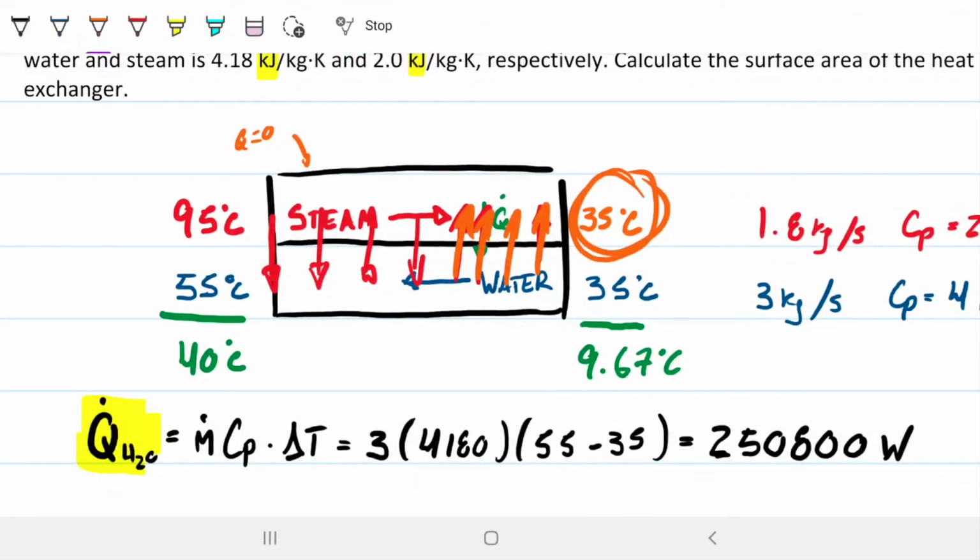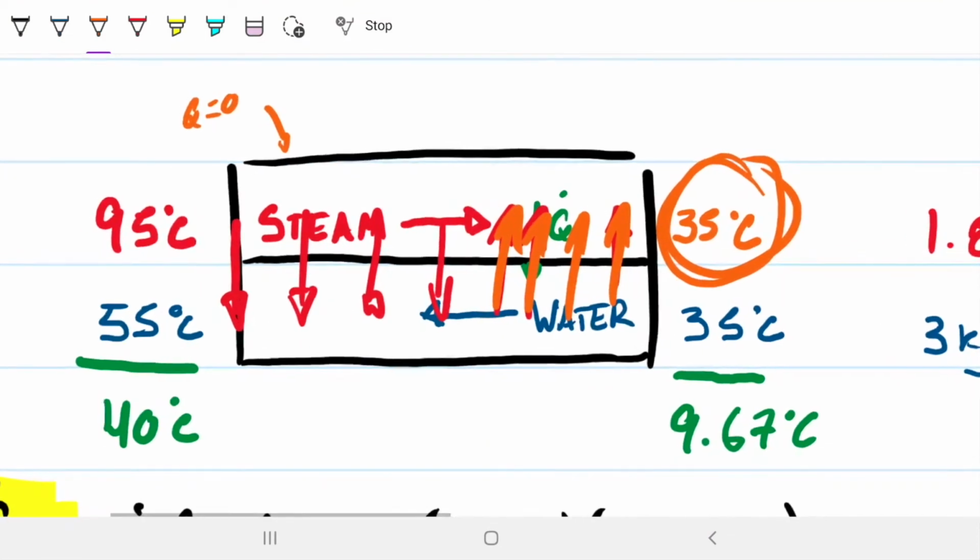So if this were the case, what would be our actual heat exchanger? Let me continue with the problem. That's one of the problems. The second problem is that we know that steam does not give away energy and change temperature unless it fully converts into liquid. So at boiling point, it's going to give away latent heat during the saturated mix phase inside the dome, for those of you who remember thermodynamics.